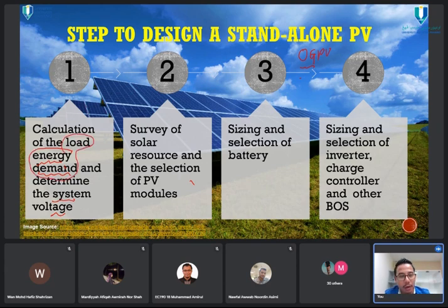It's all about the loads that we want to use in our PV system on that particular schedule. If we plan to use 20 LED bulbs and 1 unit of portable DC aircon, for example, then our PV design, our size in watts, must be based on that energy demand.